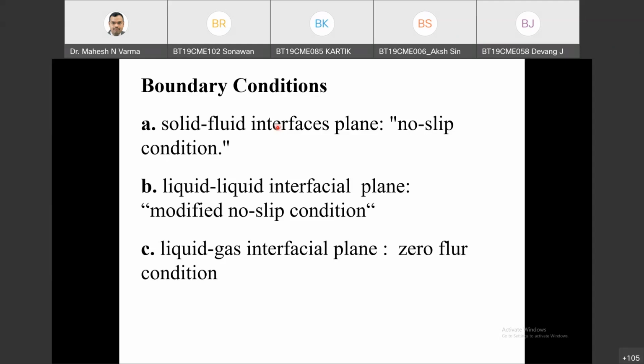For that information you need some mathematical input. I know velocity is 0 at r equals R, and the problem is symmetric: r comes to 0 and then increases again. Velocity will be maximum at the center, so the gradient will be 0 there. That is the condition for a maximum, coming from mathematics.